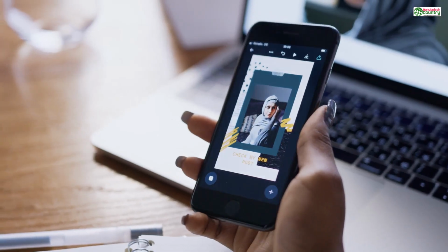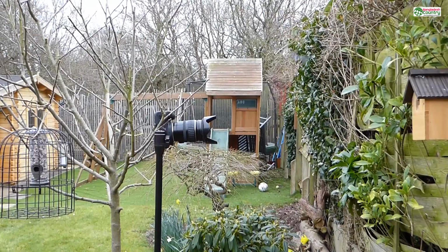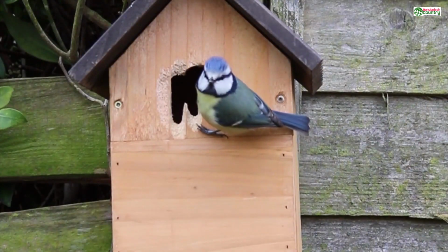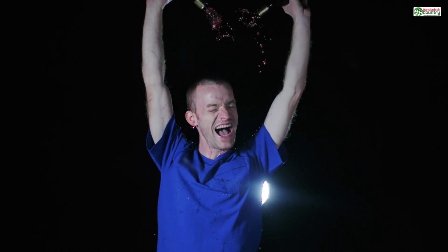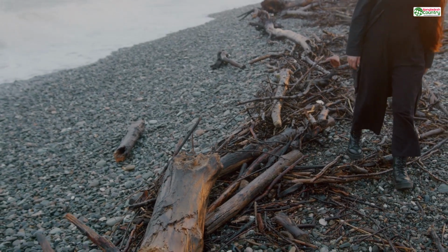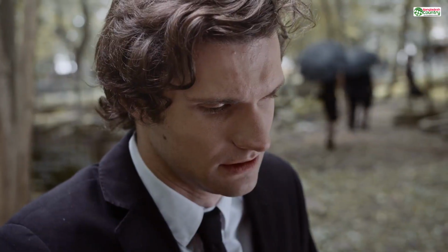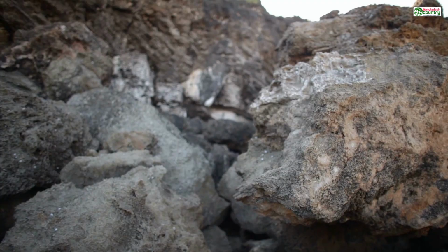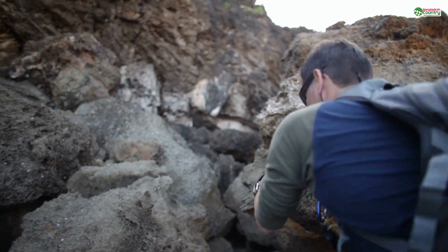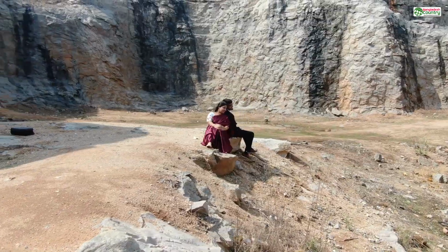First, you have the traditional standard supports. You might also hear them called linear or accordion supports. These are like pillars or thin walls that go straight down from every single point of an overhang to the build plate. They are the brute force method. They are incredibly stable and reliable, providing a rock-solid foundation for the overhangs above. However, they have downsides. They use a significant amount of material, which increases the cost and print time.